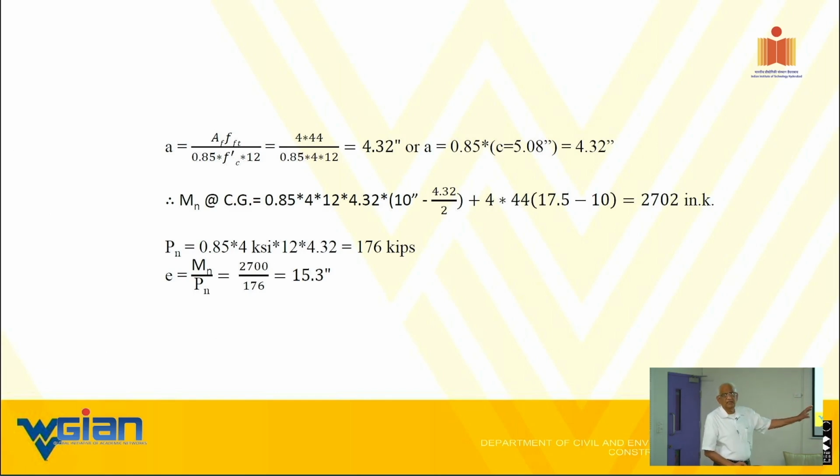I kept everything same except doubled the area of GFRP. How much increase in cost do you think I had in terms of the overall column? But I got a 50% increase in the capacity. So for a pittance, for about a few dollars of extra reinforcement, I got 50% increase. So as a designer, you need to optimize the response in this manner.